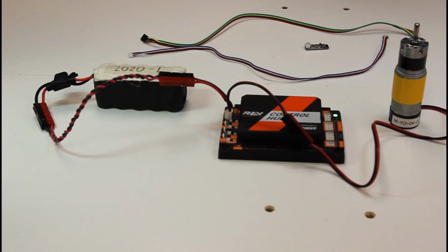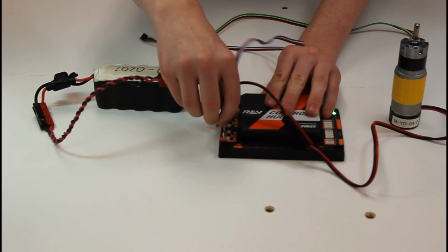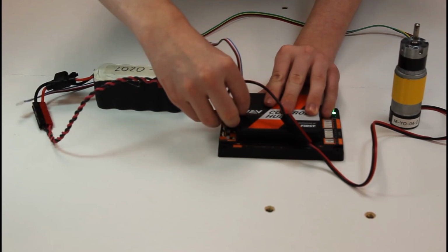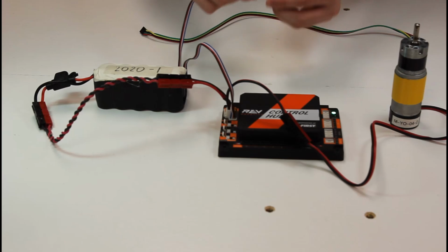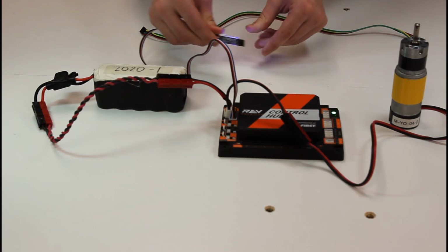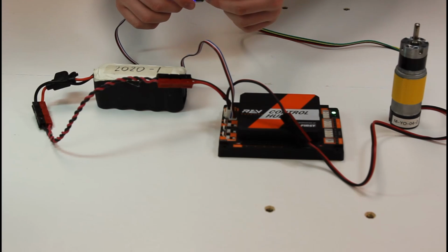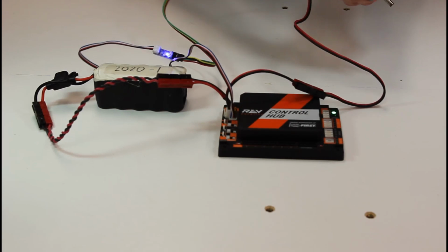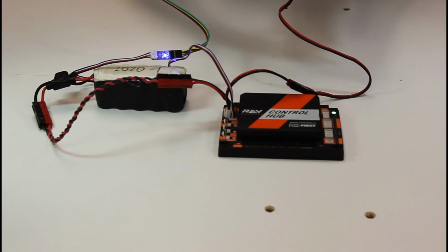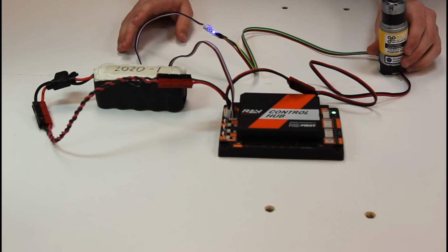So now that we're ready to plug in our motor encoder, first thing we need to do is get this I2C cable and plug it into the port directly below your motor. And then get a level shifter and plug it into the I2C cable. Next, get one of these motor encoder wires here and plug it into the level shifter. And now plug that into your motor. And that's it. And we're ready to program an encoder.